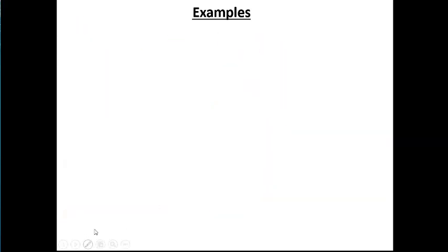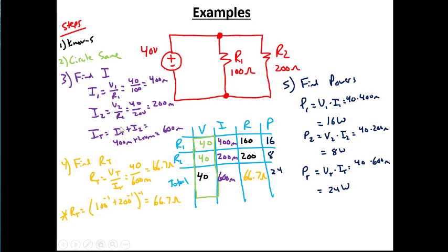So for this, actually, just a sec. So one more thing I want to put on here is we always are concerned about the current, what the current's doing. So let's draw the current on here. So we have current here, this is the total. This is going to be 600 milliamps of current. It's going to come into this node as 600 milliamps, and some of it's going to go up, and some of it's going to go this way. And so the current that goes to the right, it's based on the ratio of these resistors. More current goes to less resistance.